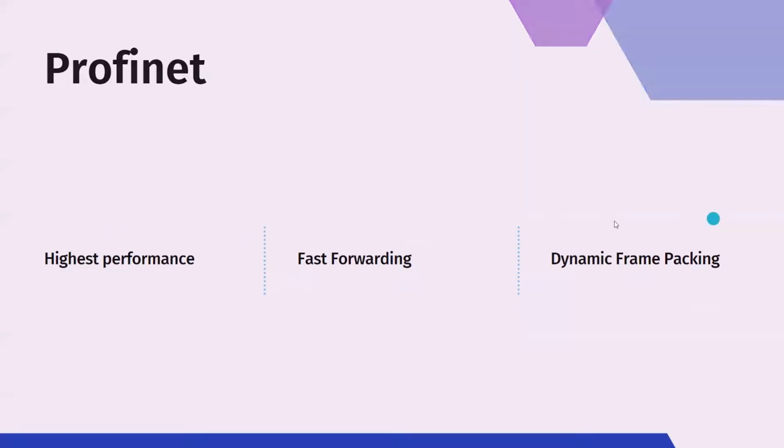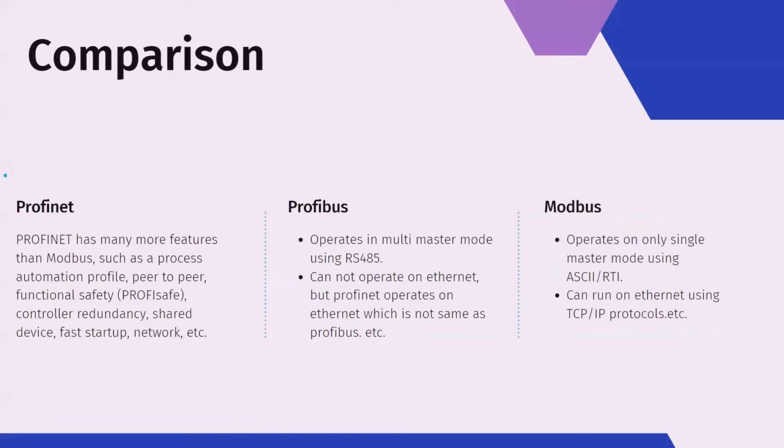Let's now talk about close relative alternatives and comparisons with them. Modbus is an open protocol that was designed by Modicon. It is accepted as a de facto standard. It was designed for transmitting non-critical, non-deterministic data between PLCs.